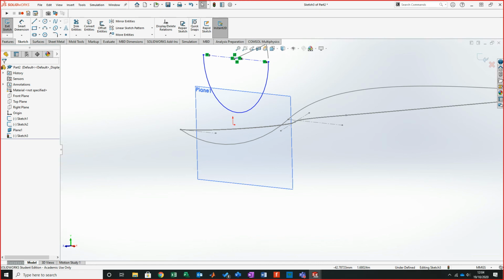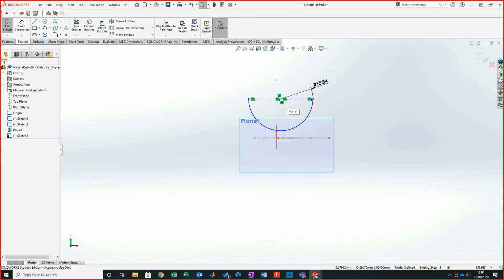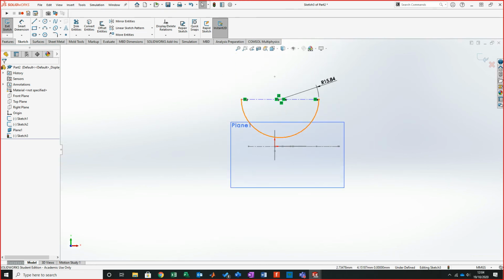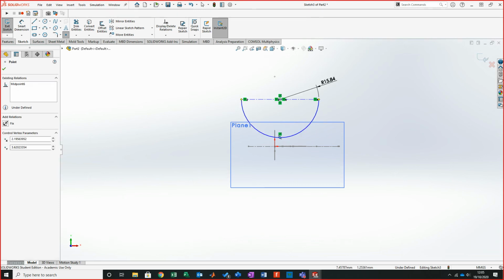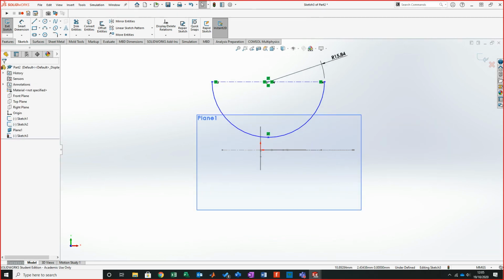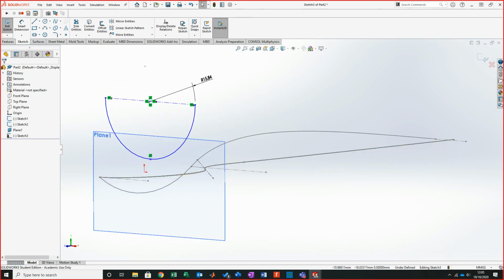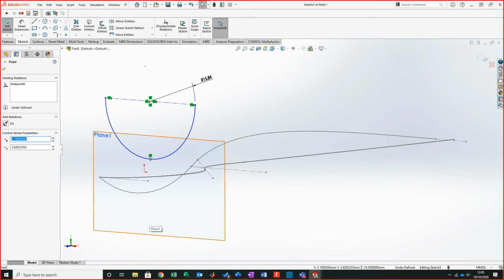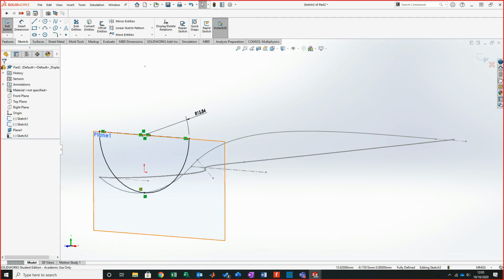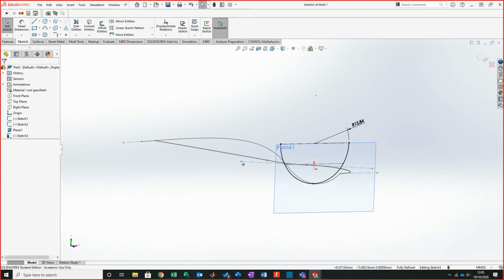Now, a few ways with it. If I just come back down to here, getting the arc quadrant is a bit of a pain and is quite tricky. There's a few ways I could come down. I could locate that marker onto there, just to put it there. So at least then I've got an arc quadrant marker. Because if you remember, when you're piercing, you need a point and then where you're going to pierce to. So if I press Control now, select my point, select my arc, and then I pierce, that puts it into position. So that's one way of doing it.